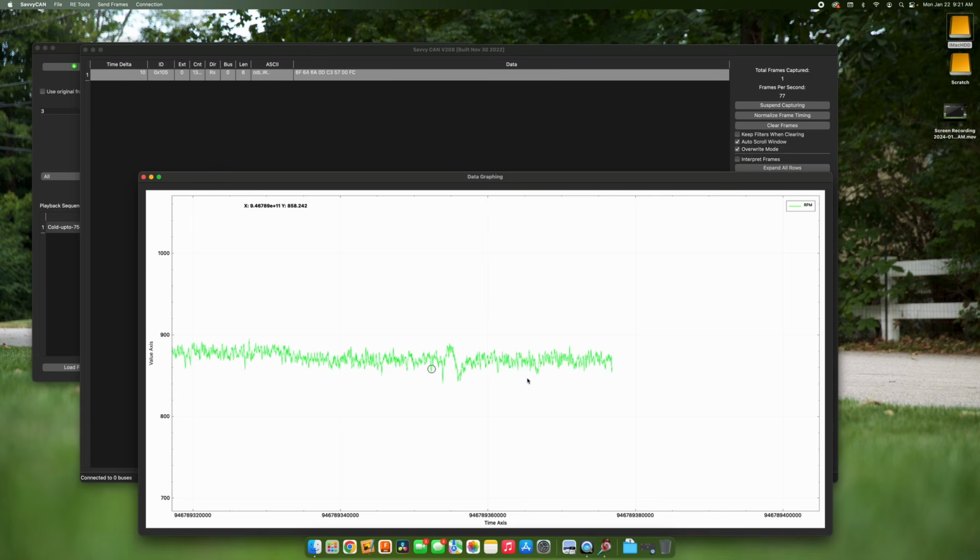We can go back in the car and hit the throttle a little bit here. We've got throttle position already, so we can watch throttle position go up in concert with the RPM, which is pretty cool. All right, we've got 3 telemetry attributes pulled off the CAN bus now: RPM, throttle position, and brake switch.